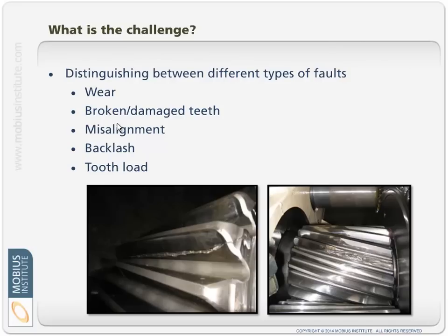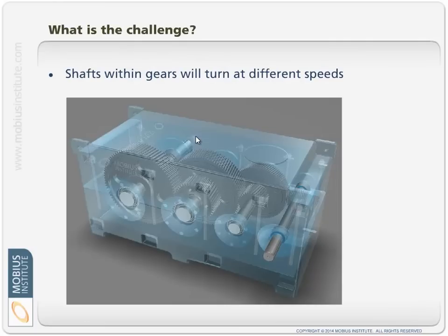You need to do time waveform analysis, and I know I mention it later, but you should also be performing oil analysis to make sure the lubricant itself is good, and wear particle analysis to see if there are any signs of wear. Anyway, let's move along.